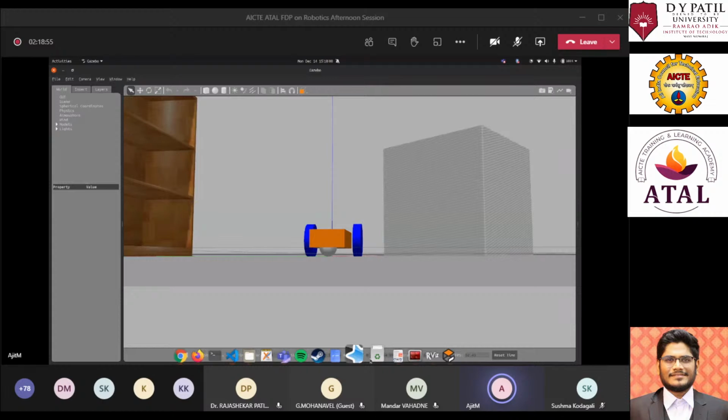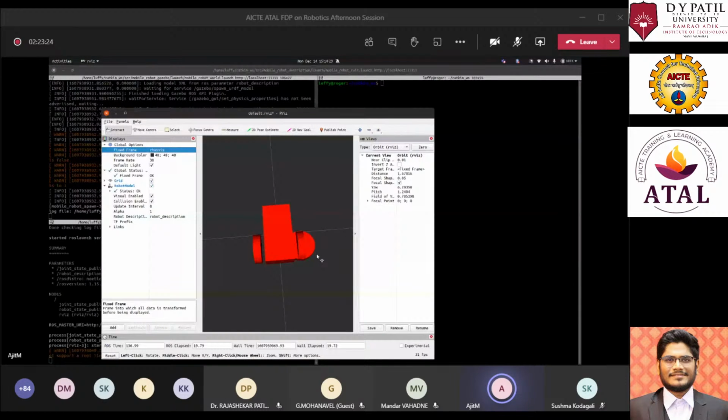So now you can see, if I just start the collision, the collision hasn't been shifted since we gave the rotation to that collision model. But here you can see the visual model is shifted in the pitch and yaw axis. So if we change it in the pitch axis, hold on, I'll do the changes one by one so you'll understand what is happening.